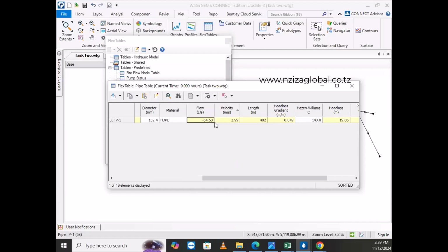Because I saw one of you also has flows which are negative. There's some who has. Yes? Yes, you have it. No one else? So this means my water is going mostly in the wrong direction, or my pipe is drawn in the wrong direction.